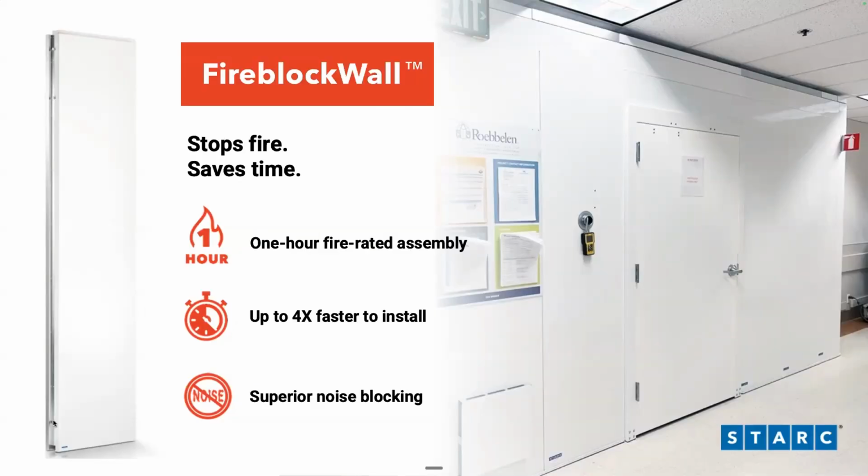RealWall and light barrier can be used when there is an active sprinkler, but in the case where you don't have that and need a 1-hour fire rated wall, we have a system called FireBlock Wall. FireBlock Wall is a modular reusable 1-hour fire rated wall with all of the key components to build out that wall. It's constructed with different sized fixed panels. There's 92-inch panels and 104-inch panels, and then extensions on top of that. So you can build a wall anywhere from 8 feet up to 10'6" with these panels.